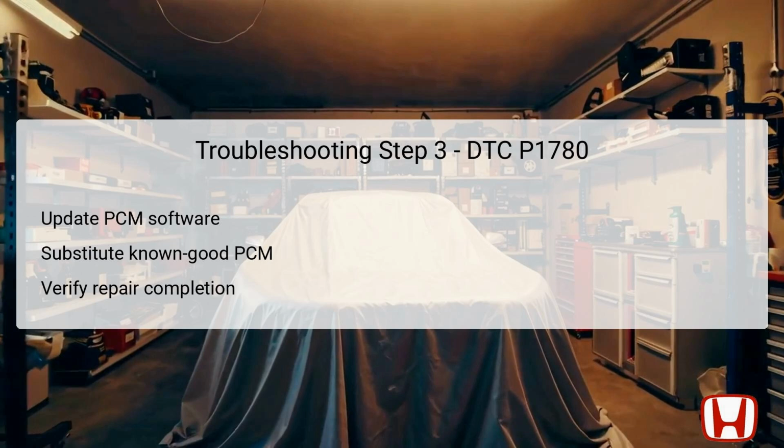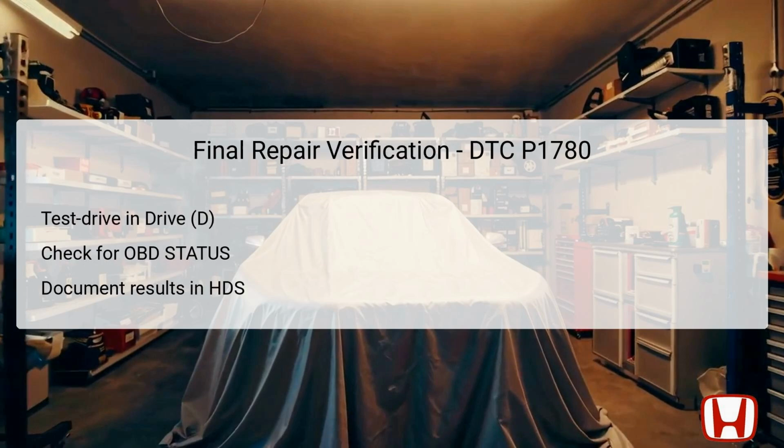After making these updates or substitutions, conduct a repair verification step. This entails the same test drive of the vehicle, monitoring the OBD status for P1780 to evaluate if the issue has been resolved. If further issues or codes arise, continue troubleshooting as necessary. Final repair verification is essential to ensure that the corrective actions taken have resolved the issues triggering DTC P1780.